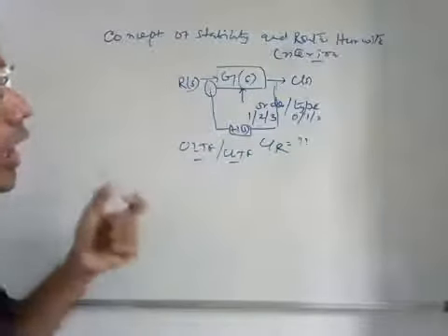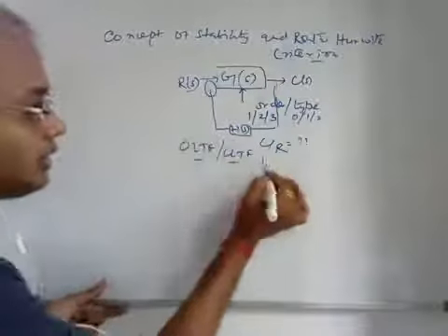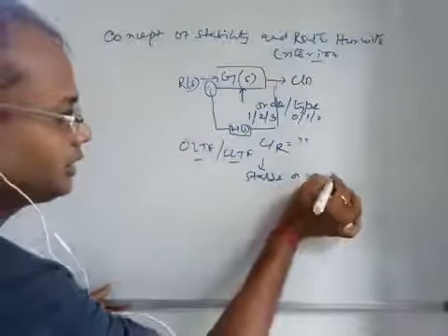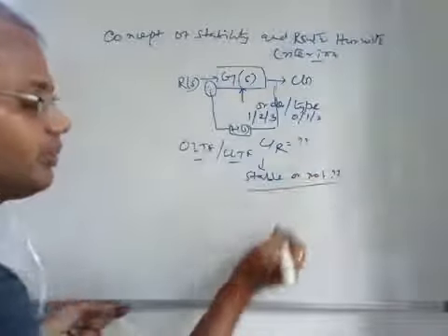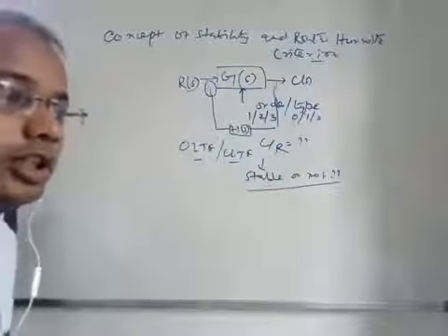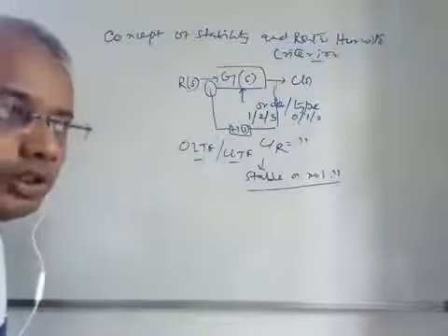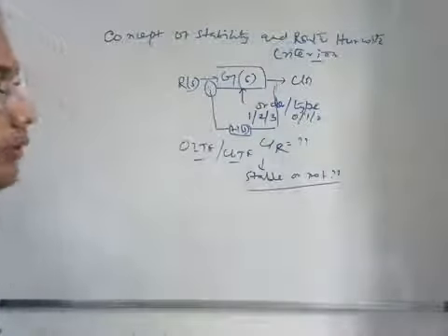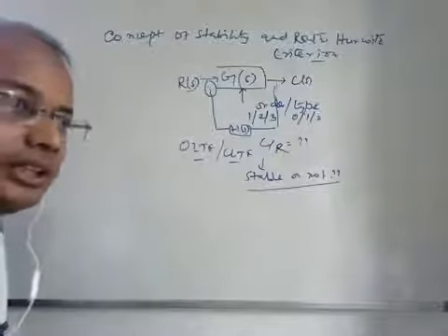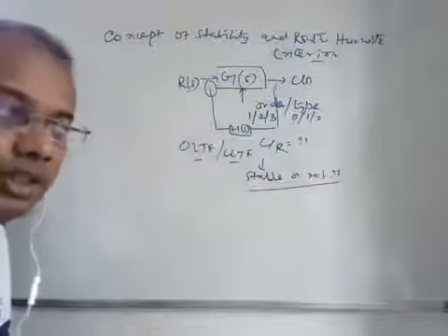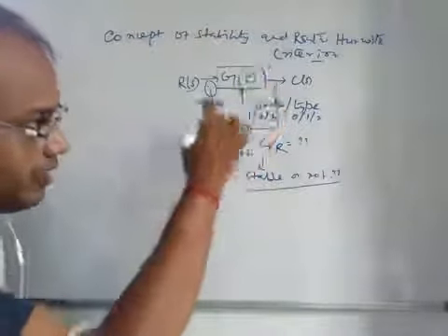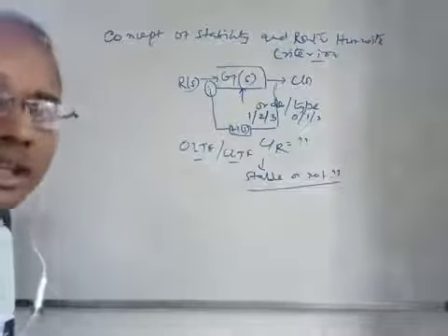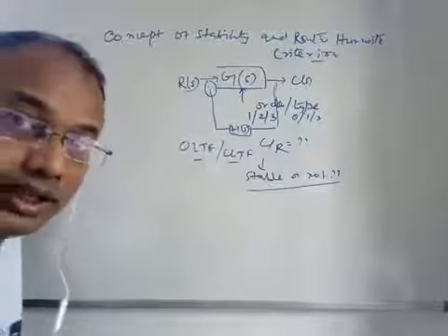So our aim is to find out whether the system is stable or not. If the system is not stable, you are not going to get the desired output, and the system is not valid in real life. So either the system is open loop stable, or you can add some kind of feedback, or there are different kinds of controllers you can add to make the system stable.